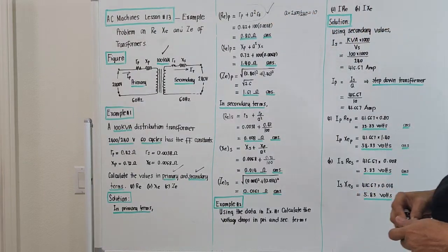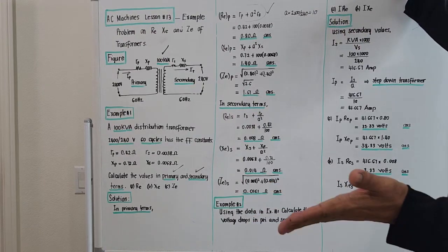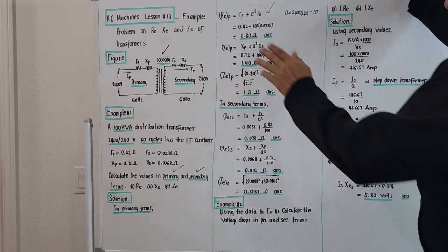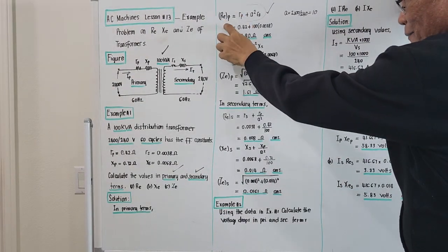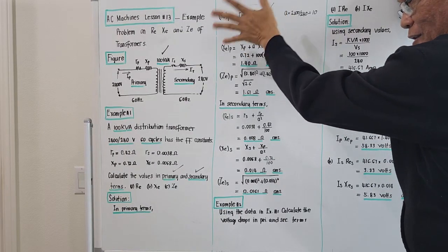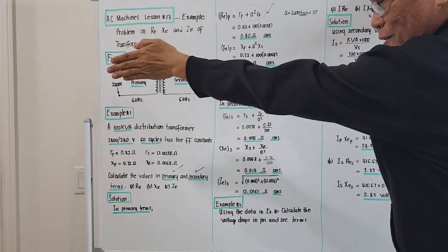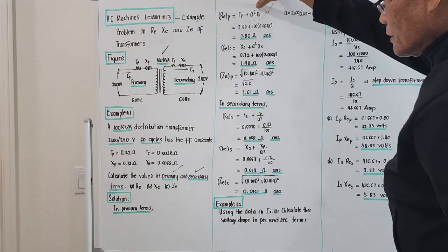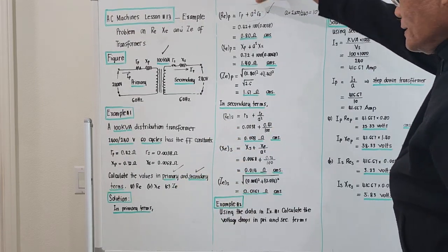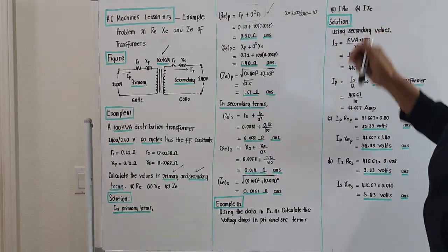Right? So this is now just a matter of direct substitution. The problem is if you could not recall your equation, I will repeat it. The equivalent resistance referred to the primary should be equal to the resistance of the primary plus the resistance of R sub S referred to the primary. For it to be referred to the primary, it should be multiplied by the ratio of transformation squared. Okay, let's try to compute for the ratio of transformation.